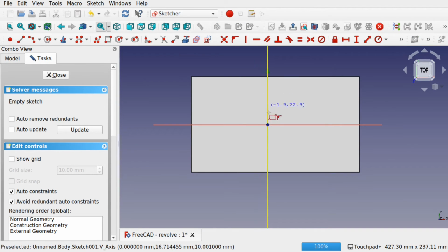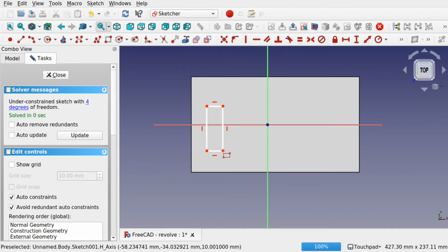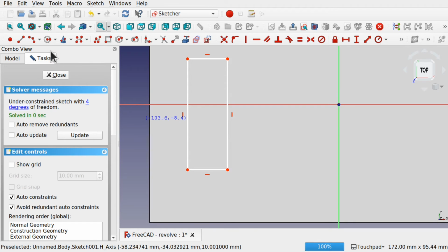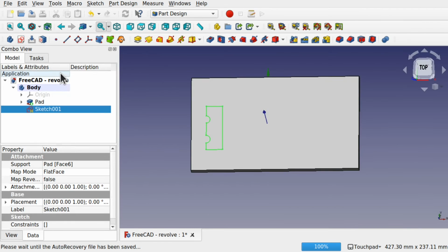I'm going to click on the surface and create a profile on there. Now I'm going to create something basically along here. So I'm going to create a square. And I'm going to put some circles on the square. Let's put them on the outside. Not worried about position, this is just for demonstration. And we're going to trim these. So trim that one and trim that out. Trim and trim. Hit close.